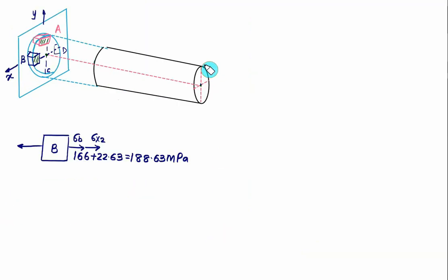And one last effect you have to show is the torsion. So torsion is shown acting on the free end in this direction. That equals torque T. So if you look from the Z axis, it will be anti-clockwise. So on this end, it will be clockwise. It will be like this. If it is clockwise, then on this face, it will be anti-clockwise. So I will show the anti-clockwise face of the torque. Now we are interested in the member B only, so the shear stress will act in a vertically downward direction on this face, that is, it will act in a downward direction.